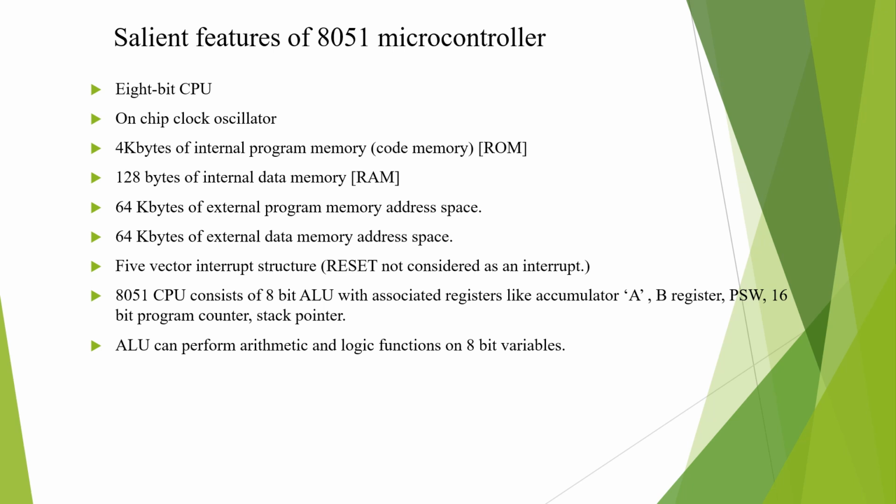There is also 128 bytes of internal data memory, which is basically the RAM. It is an obvious question: if my program is more than 4 kilobytes, what will happen? In that case we can connect a 64 kilobyte external ROM with the 8051.